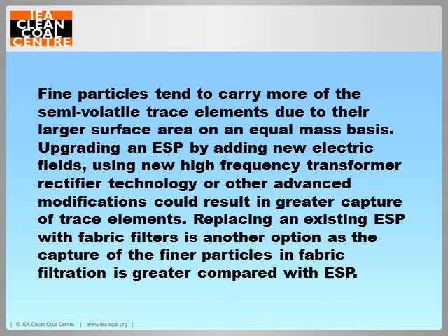Electrostatic precipitators have lower capture efficiencies for ultrafine particles, as smaller particles are more difficult to charge to a sufficient level for electrostatic collection. The problem is exacerbated with high resistivity fly ash. Particle agglomeration systems may provide an economical solution to fine particulate control from ESPs as well as fabric filters.